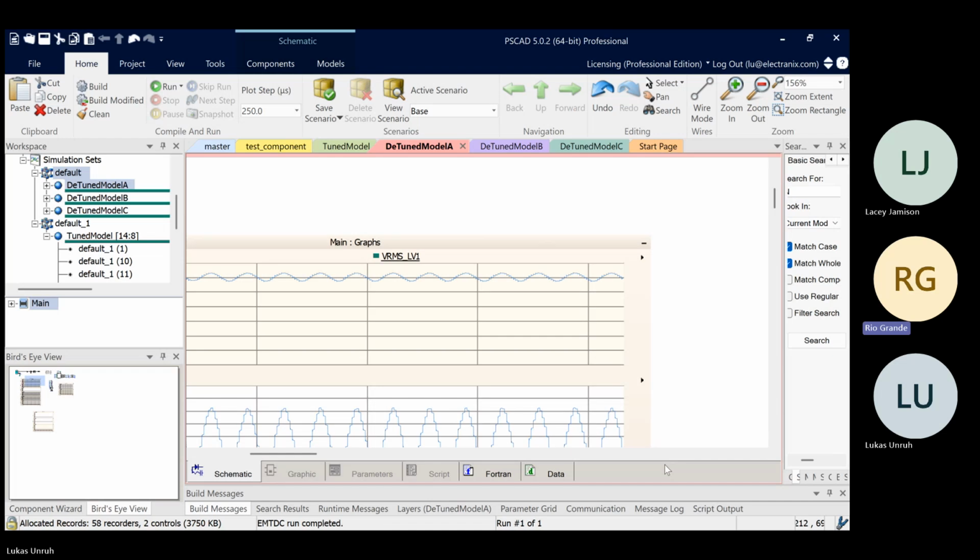Yeah, you basically have turned down the gain on those voltage controllers. You theoretically could restudy and retune them to optimize, to get a faster, bigger Q response if you wanted to, or needed it afterwards. But you don't have to. And it's much less dangerous, well, risky, I guess, to do it that way than the other way. It's much different when you're connected to a strong system and that system gets weaker over time, because then you're going to start seeing these types of things. Going the other way around is different.